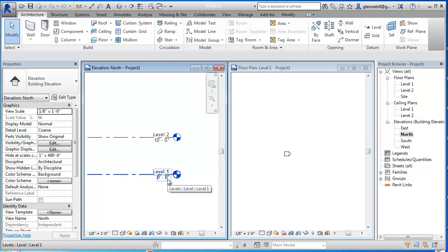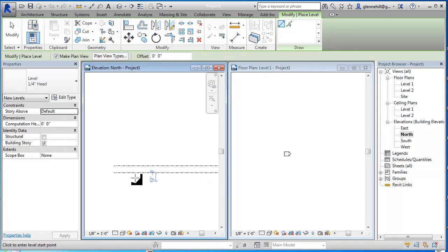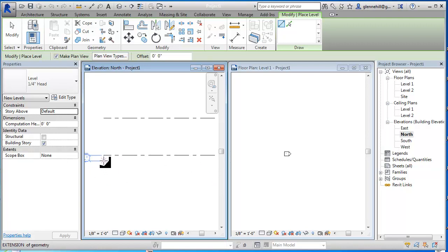Now, in construction documents, often these are set to the actual survey elevations. But in this case, we don't need to do that, nor do we really want to, because it's hard to design and add to the document. So we're going to create a level here in architecture. We're going to go up here to level, and I'm going to create it 1 foot below